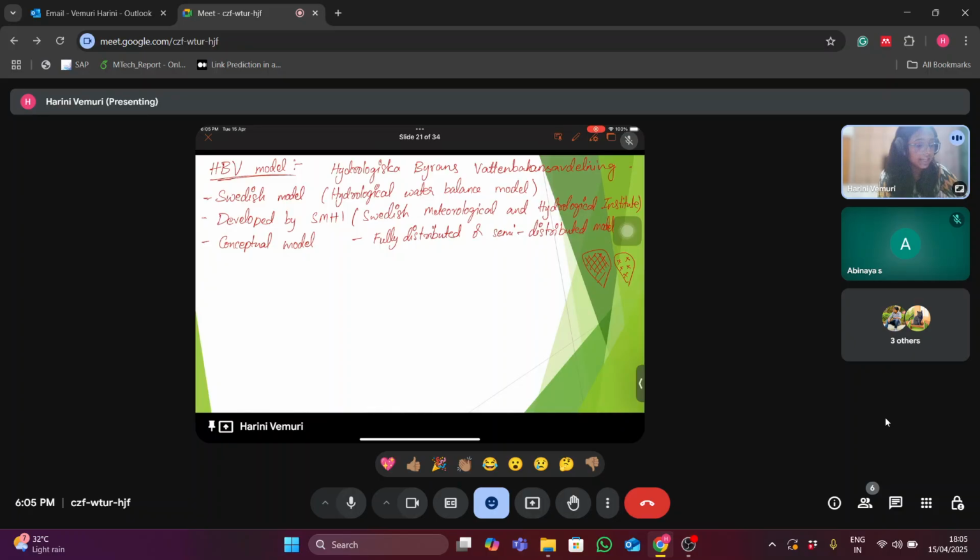That's why we will get an idea of how the spatial variation of any hydrological or meteorological variable is in the basin using a distributed model. But in case of a lump model, you will get an averaged idea. For this entire basin, we'll have only one single time series of stream flow as output. Then we won't understand how it is varying spatially, right? So we only get an average idea of how the basin is overall performing in generating runoff from rainfall.